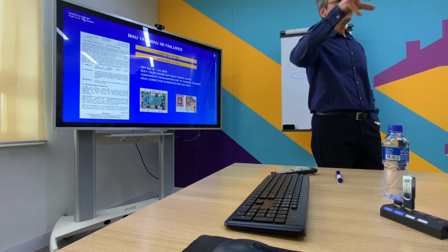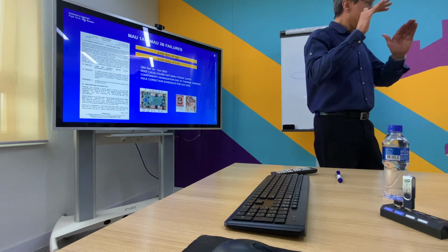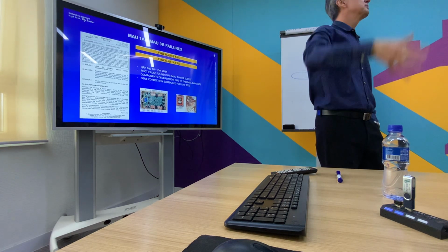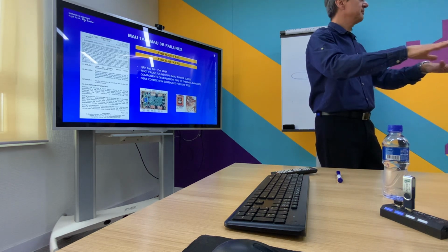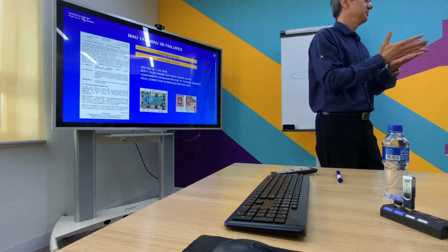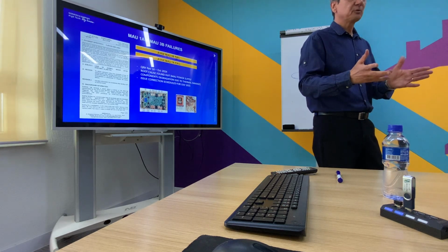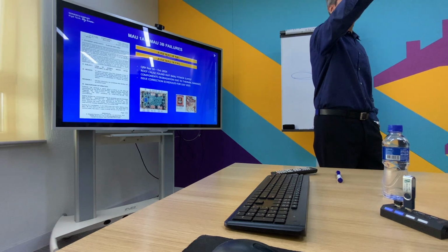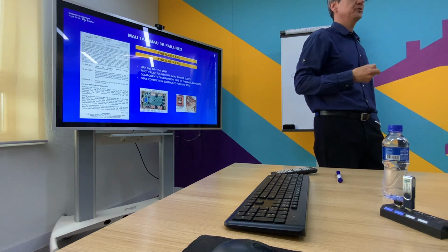Nowadays, Embraer updated the QRH procedure, stating just read and do. Just in flight, press the brakes. If you get brake fail, be prepared to use the parking brake. If you don't get brake fail, you have the normal brakes, just half, because you're going to get the brake faults. You have the outboard or the inboard, I don't know by heart. But the updated procedure was to press the brakes in flight to check if the message will appear and to be prepared to use the parking brake to stop the airplane.